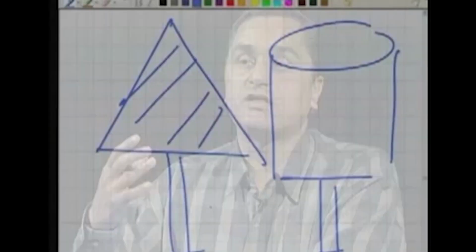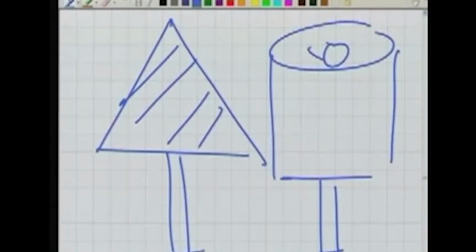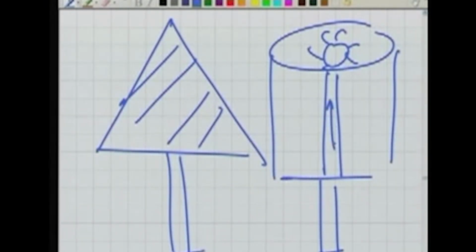Some signals are there which make use of light, because you want to do the triangulation at night. If you want to do it at night, your signal should have some mechanism by which, let's say there is an electric bulb and here is a slit. So this slit can be seen if this bulb is switched on, or there is some lantern or something kept there which is producing light. So you can see this light from a distance. So this kind of signals are called night signals.